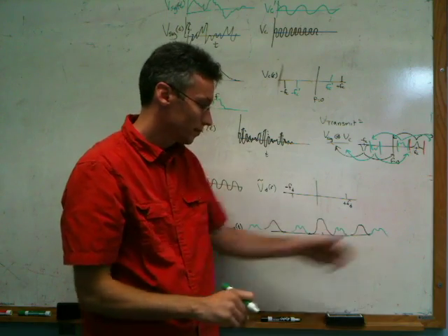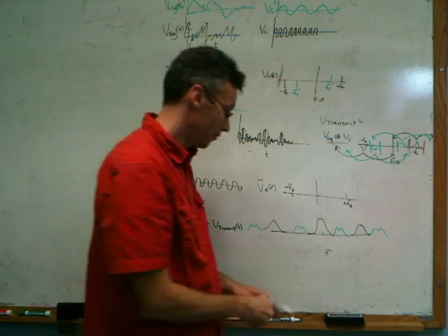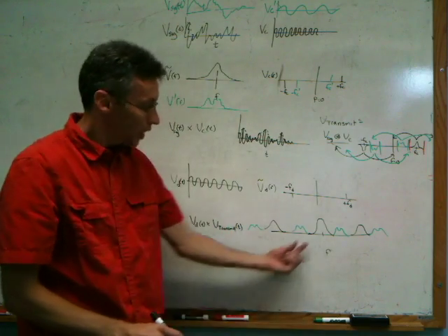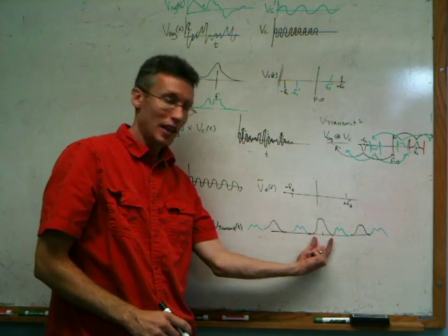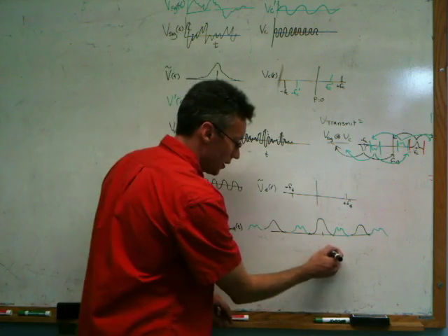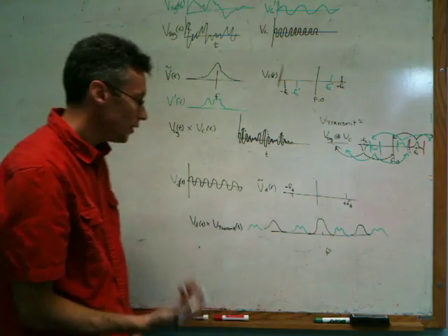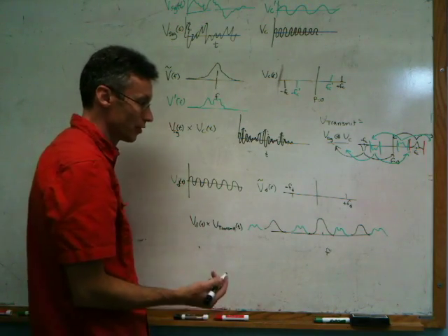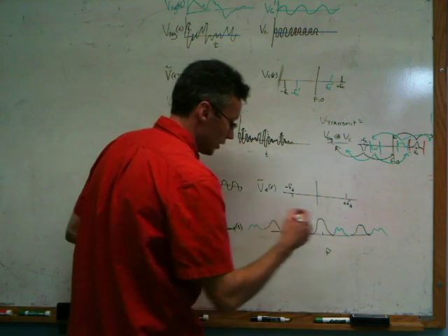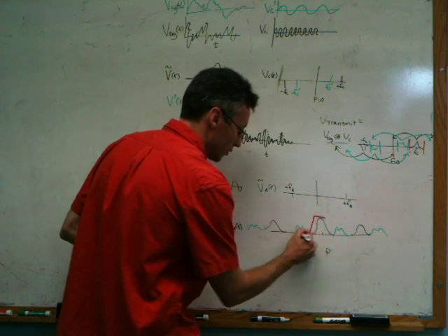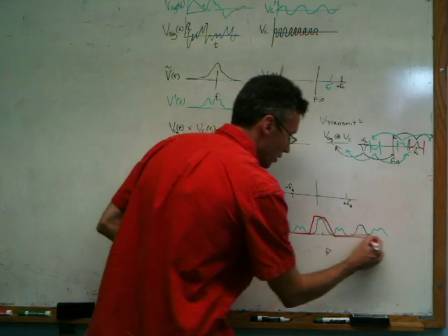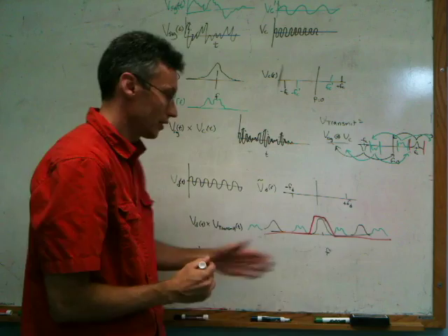So we have this really complicated and full frequency spectrum, which has our original signal at its appropriate frequency, but has all this other junk. And so the way we deal with that is to filter out the other junk. Right? We want to put in a low-pass filter that essentially blocks out this other stuff.